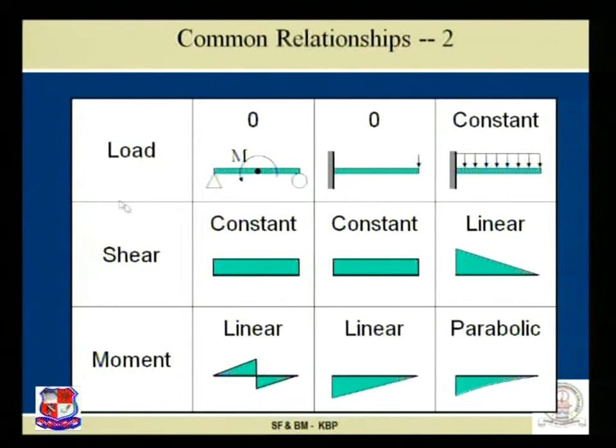Now the next one. For a beam subjected to a moment or a couple at a particular point, there is no effect on the shear force diagram at that particular point. I will revise the statement once again. For a beam subjected to a moment or a couple at a particular point, it definitely affects the reactions and changes the value of the reaction, but there is no effect at that particular point on the shear force diagram.